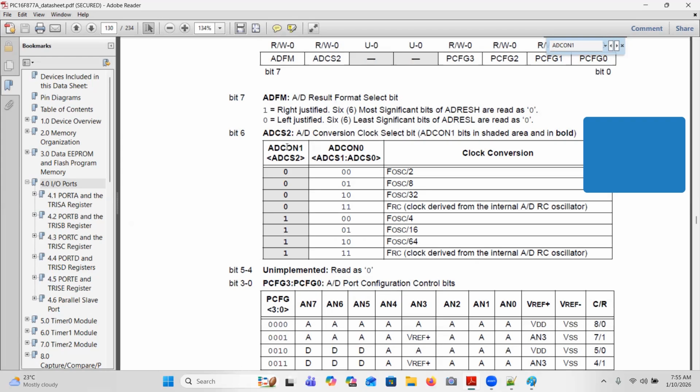Most of the time we won't use the microcontroller operating clock directly as a peripheral clock, because usually peripherals will be slower than the microcontroller. So whether we use the operating clock as such, or divide that clock to reduce its frequency further, that we are defining